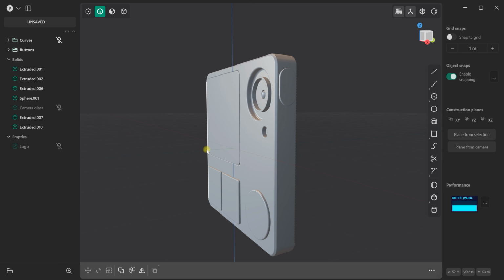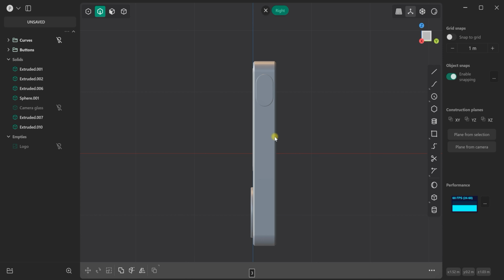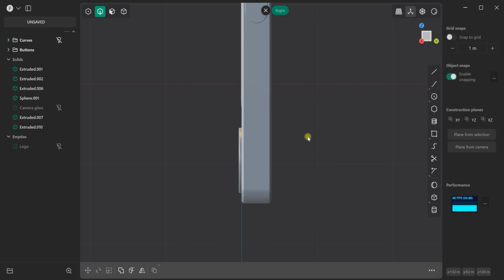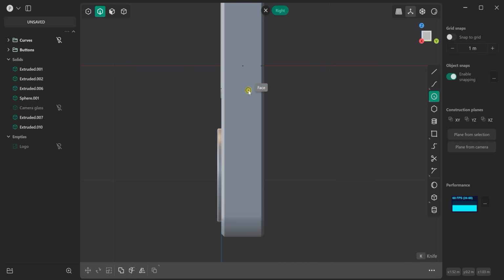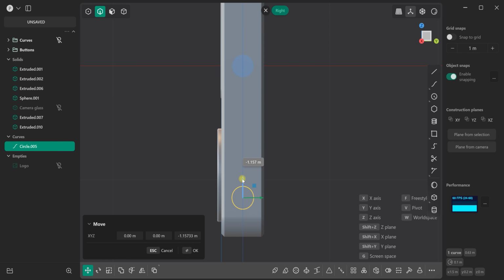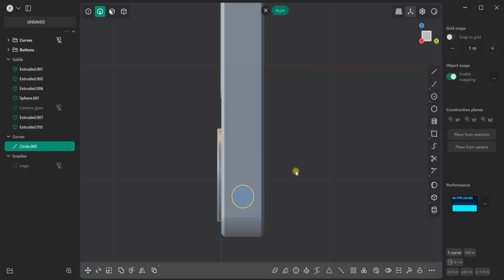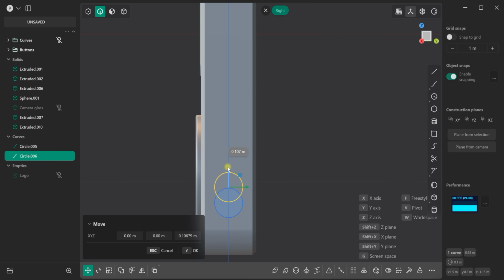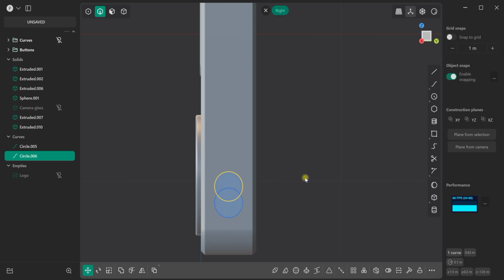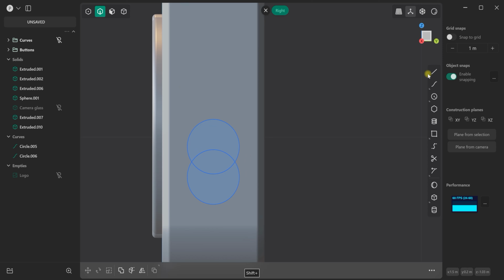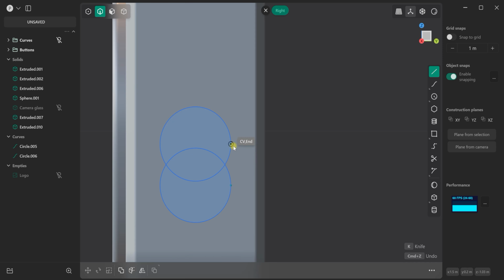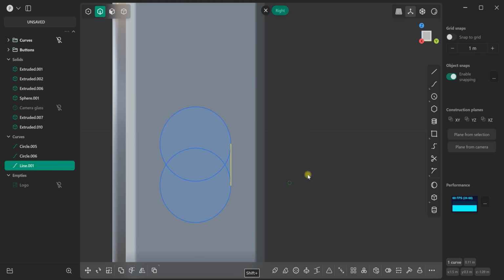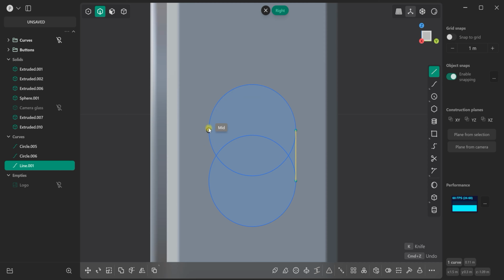In the right view, we're creating some kind of holders. We've already done this at least 5 times for this tutorial. Everything is so simple. We're using center circles, creating tangent lines, trimming unnecessary parts, joining our curves and lines, and extruding them in face mode. Something like that.